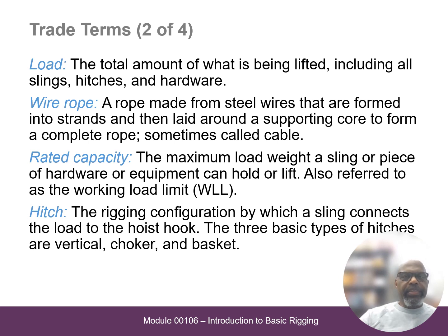Load, that's anything that has weight to it that you need to lift. So a load can be trash, or it can be bricks or a skid of tools. But a load is the total amount of what is being lifted, including all the slings, hitches, and the hardware.